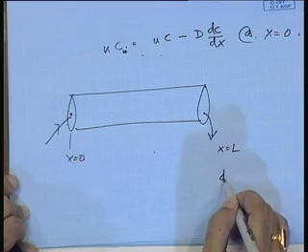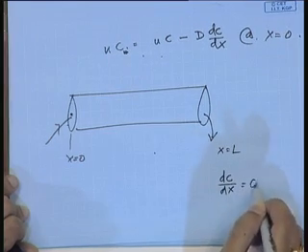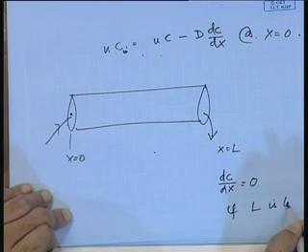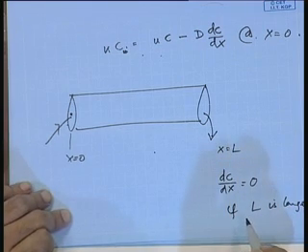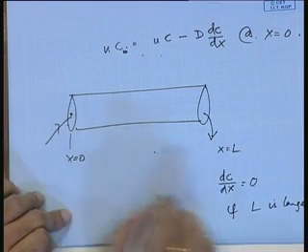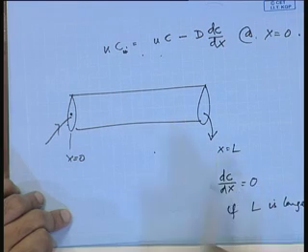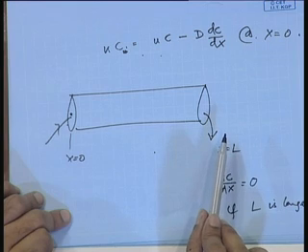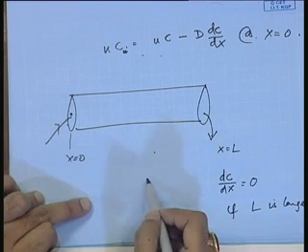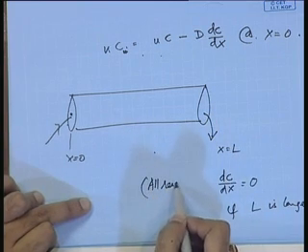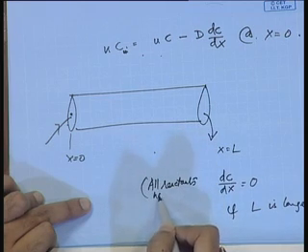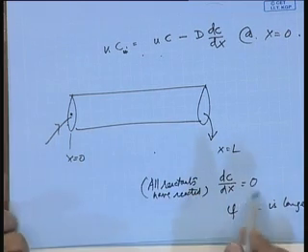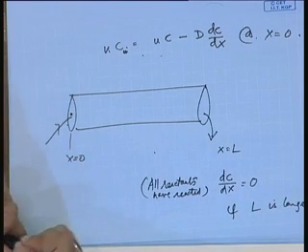It would typically be del C del X equals 0. Okay. Why? If L is large as compared to, say, the radius of the reactor. So, if the length is very large, what does this mean? What it means is that all the reactant has reacted, and there is no reactant left at the end to leave. This means that all reactants have reacted. Okay. So, there is no reactant left. So, these are the boundary conditions.